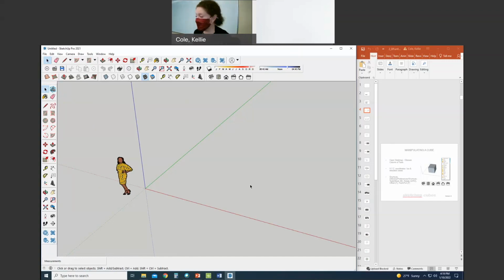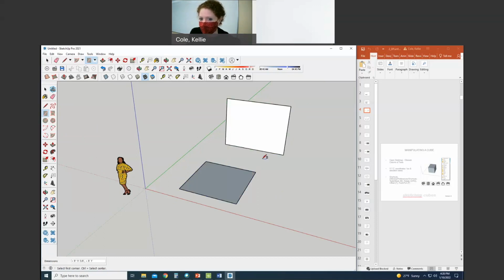So I like keyboard shortcut commands. If I just type R, it gives me the rectangle command. If you're more of a button person, it's highlighted now that you've touched R on the left-hand side, right? Draw a rectangle by clicking once, dragging it across the page, and clicking again. If your rectangle accidentally drew in the vertical dimension, don't worry. Everybody have a rectangle?